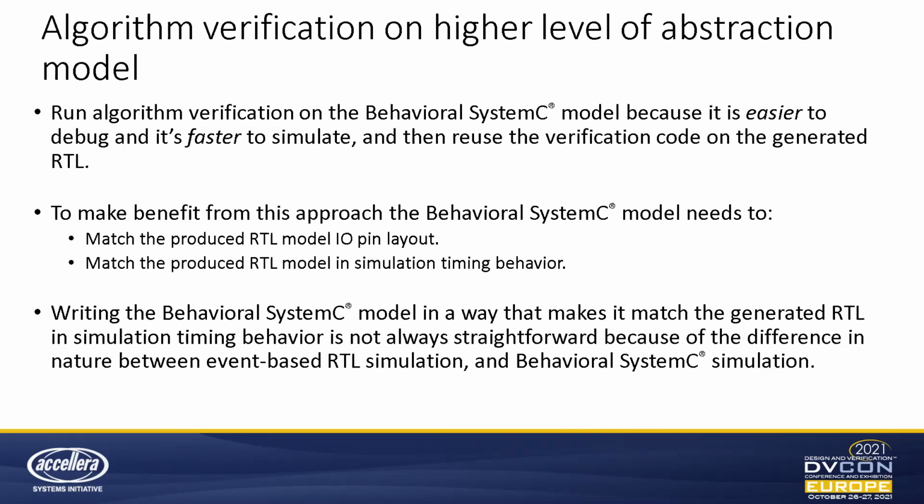To achieve this, we need this model to match RTL in two things. The first thing is the IO pin layout. So you can just change the instance inside your system and switch between SystemC and RTL because they match in pin layout on the entity. And the second point is the simulation timing behavior. To achieve this, the SystemC coding style needs to be done with some consideration.